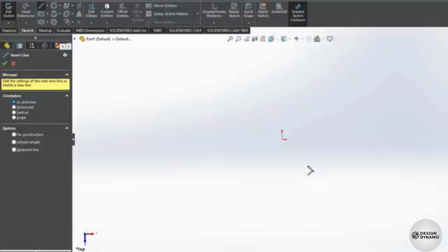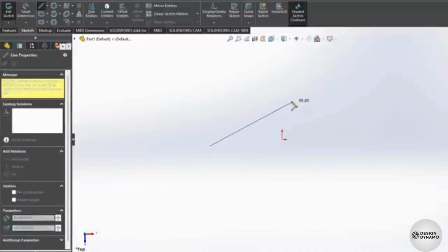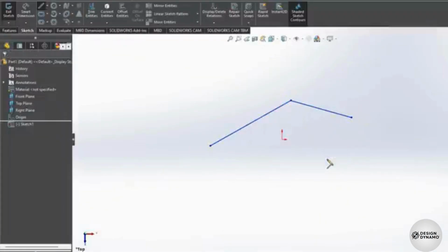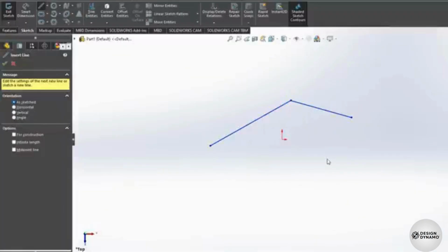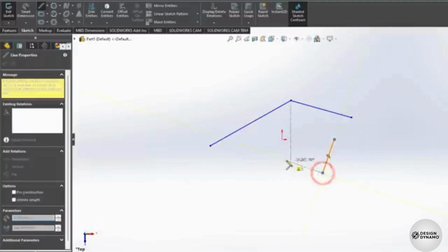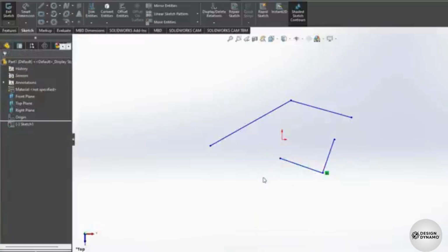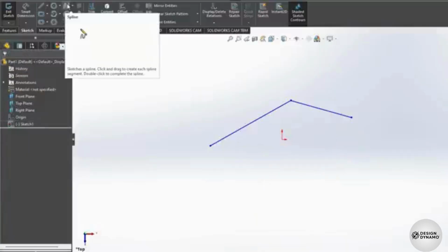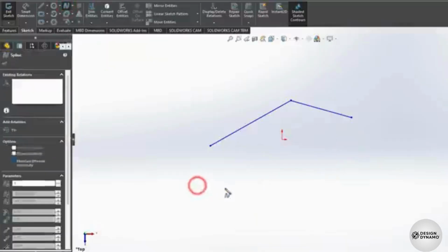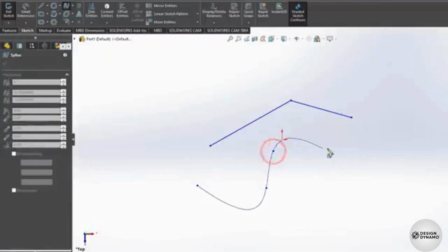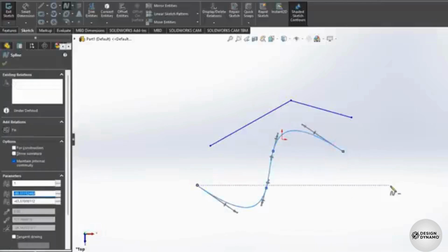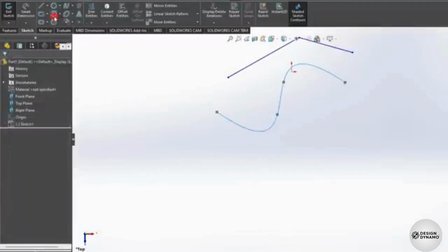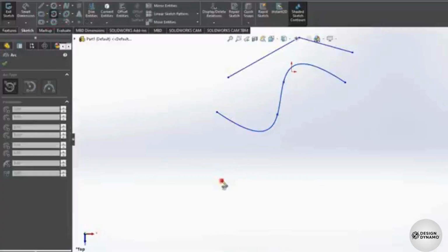At this point, you can start drawing. With the Line tool, you can drop consecutive straight segments by clicking multiple times, using the Escape key to stop drawing. Use the Enter key to always recall the latest tool and draw again. With the Spline tool, you can draw a spline curve by fixing several nodes, double-clicking on the last one to apply. Whereas use the Arc tool to drop an arc with 2 points for the radius and another for the